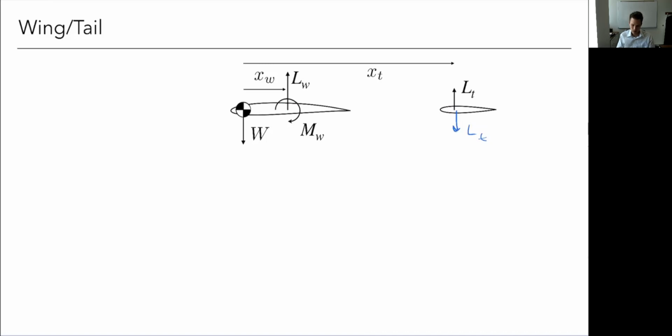But of course, going further has its trade-offs. The further away it is, the more surface area and weight I need to add to connect a tail that's further back. So there's going to be some trade-off. But this is the main takeaway for a tail: we can provide that trim. We've already got stability because our aerodynamic center is behind, but to provide a moment that goes the other direction, we need a lift that goes downward towards the back of the airplane. Again, there are compromises, not necessarily as efficient as a flying wing, but generally easier to design.